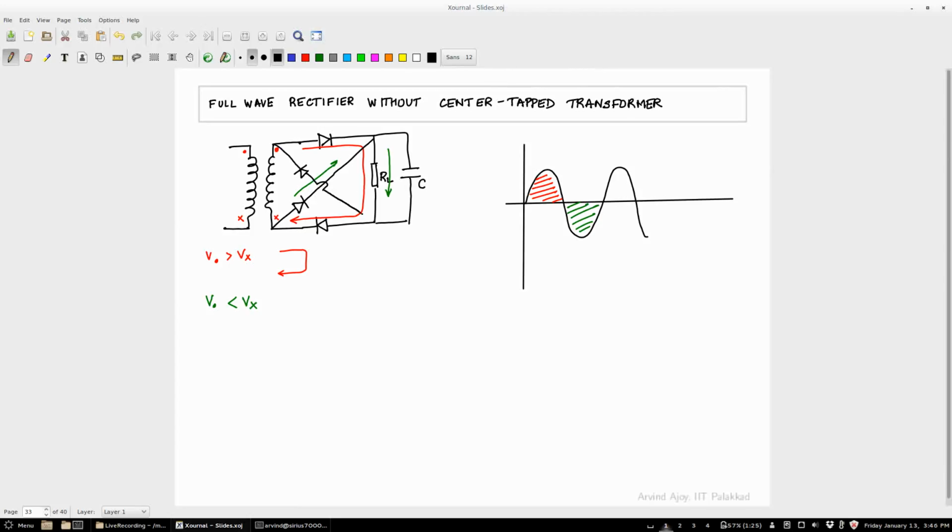I put another diode, and I have drawn it badly. This. So now the current basically goes through the load and then back through that diode, right. So the current direction will be basically the end of the zigzag. So essentially what you have done is that you have made a full wave rectifier, but you don't have a center tap transformer. Instead, you are using this connection of 4 diodes.